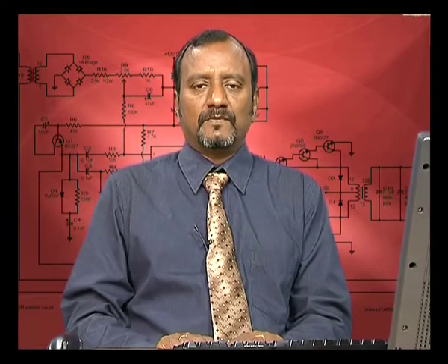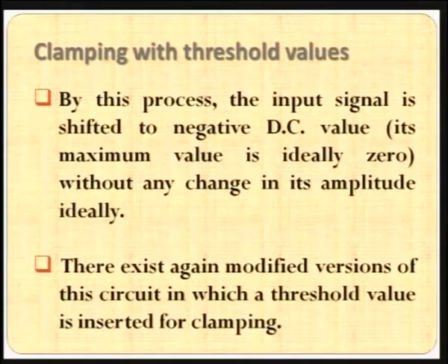We have considered in the clamping operation the reference level originally for the input was taken as 0. After that the shifting was done by the charging discharging property of the RC network that is there in the circuit.